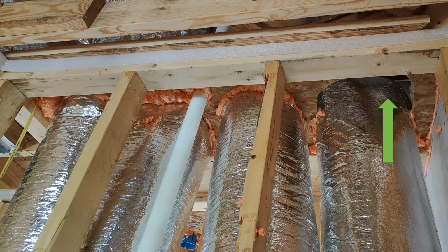According to manufacturer specs, when you look at it, that gap where the arrow is pointing is bigger than what the expandable foam should be sealing. It should be blocked by a solid material and then air sealed, but 9.5 times out of 10, that will just be poly seal if they can get it to stay. If not, it will fall through that opening. And for some reason, they're going to keep trying until it fully fills it. Not the best way to do it.